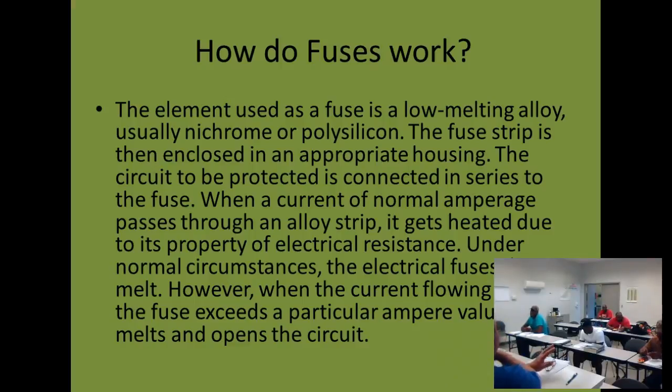All right, continuity may mean I've got a path. I've got a great path, zero resistance. Or it may go, I'm reading 6.4 ohms, but there is a path with some resistance. The only thing continuity, and that's what that symbol means, is there's definitely not an open. If it goes beep, it's not OL.